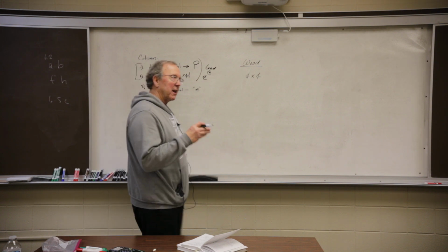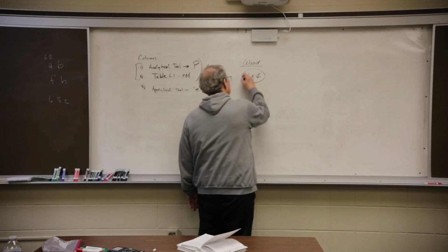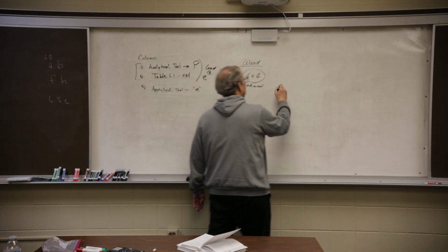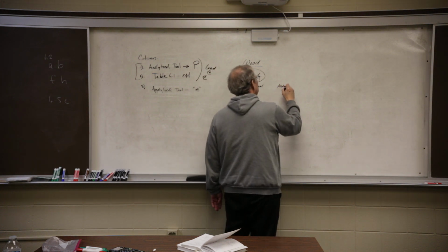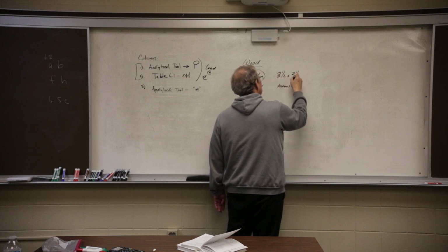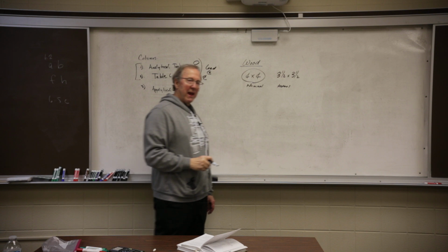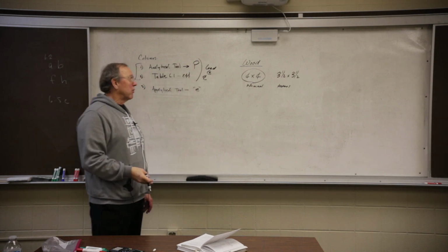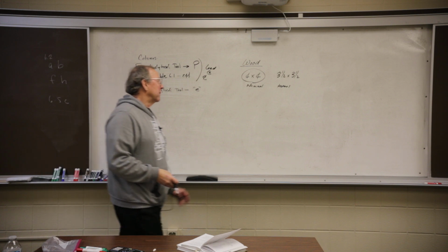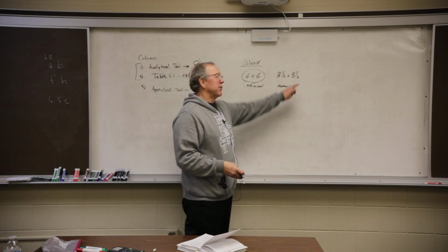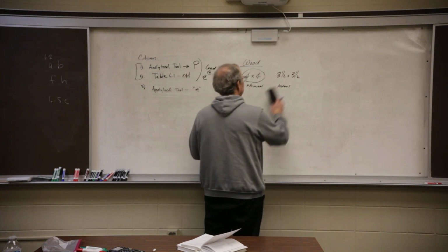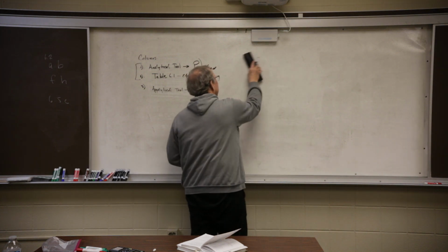It has the nominal, this is nominal, versus actual. If you take your tape out and measure it, it's actually going to be 3.5 by 3.5. So that table is calculated based on what it actually is, not what it's called. All those numbers are going to be developed off of this 3.5 by 3.5. Okay? So that's one thing. You've got to understand that.